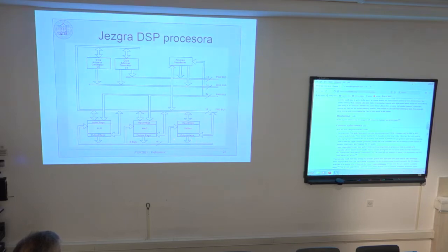And then I can use as a left argument any of those output registers on the left branch of ALU. On the left branch of ALU, I can maybe invoke MEC register 1 or 0 or 2. It has three output registers. Or shift register output register is SR0, SR1.